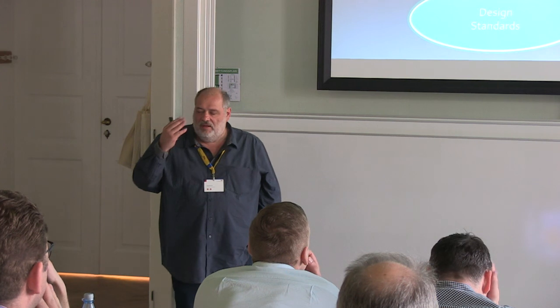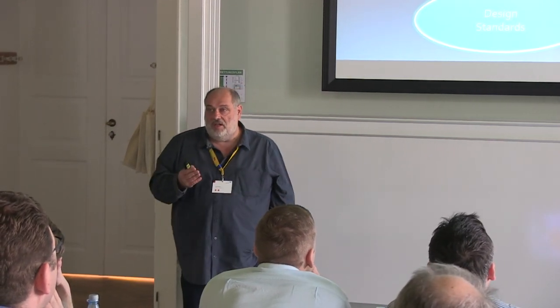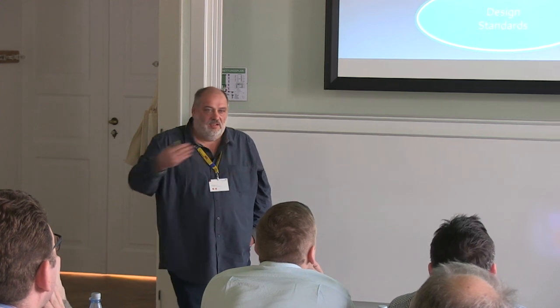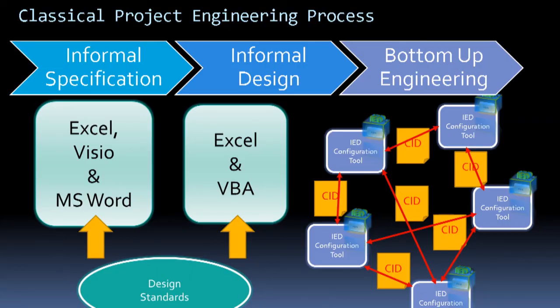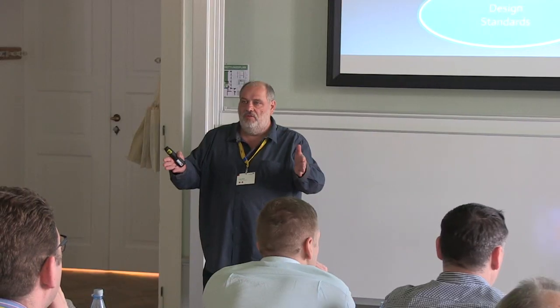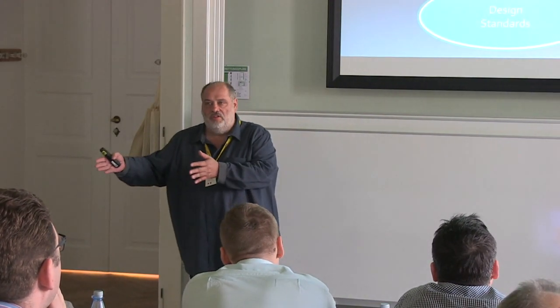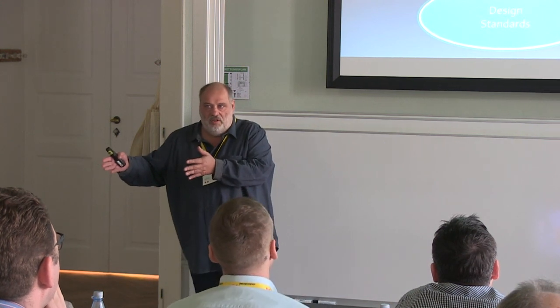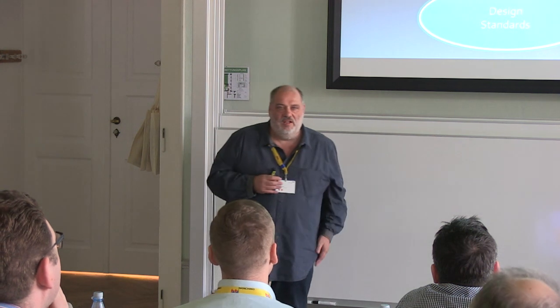If he is a little bit progressive, then he has read the standard, then he says, oh good, I take the system tool, and I take the IED tools, and then I do this with the system tool. But when he tries to do this, and he has a system with about 100 IEDs, and the first time he has made with the system tool an SCD file with 100 IEDs, and tries to load this into a relay tool, then you will see that it is really too much work to do this.